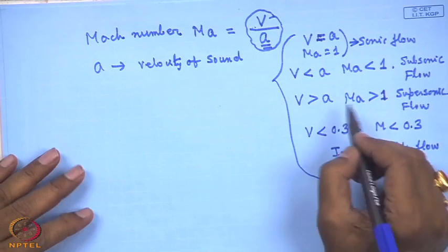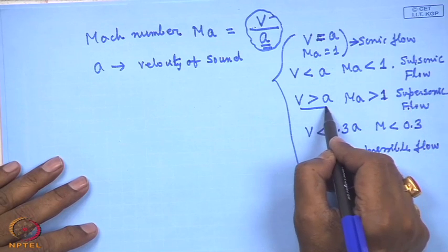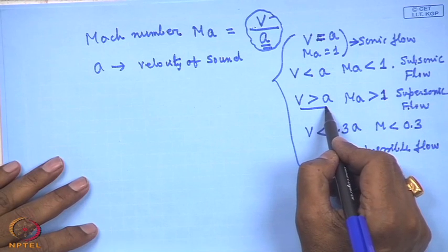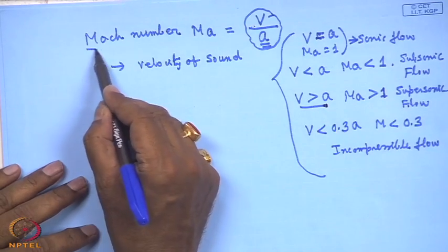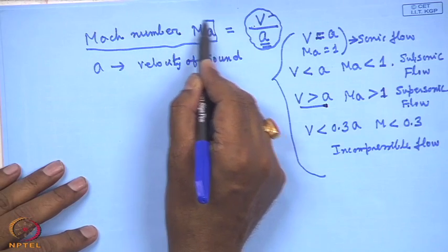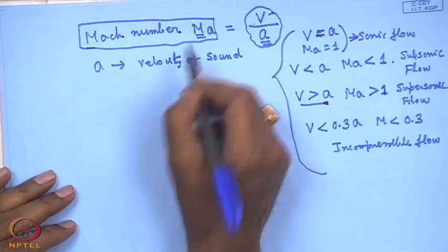Now, what happens if the flow is supersonic at any stage, depending upon its velocity? Some features are observed which cause extra losses of energy, and in a compressor extra losses of static pressure, which is undesirable. Therefore, for compressor design one has to be very careful that the Mach number of flow should not exceed the sonic level at any point in the compressor, so that other complicated features of compressible flow do not come in. This is known as Mach number considerations.